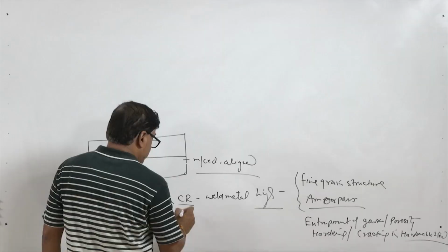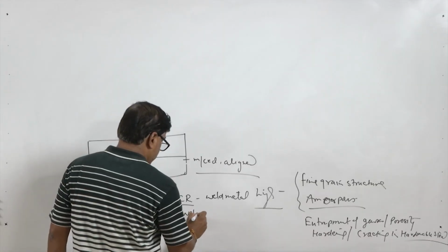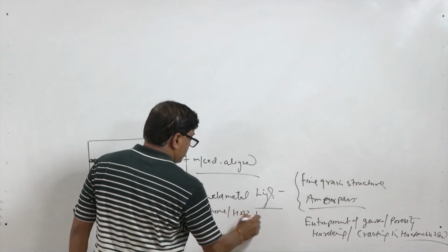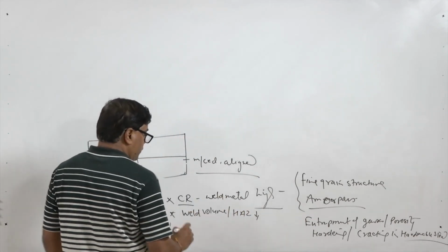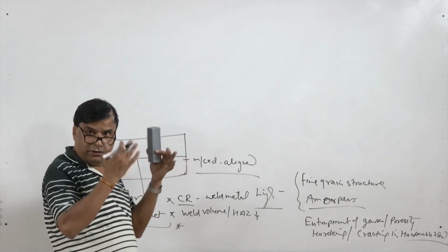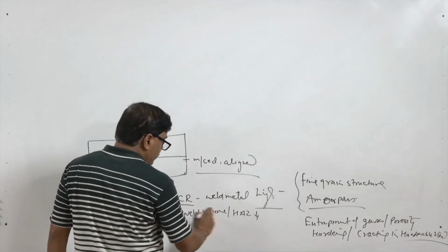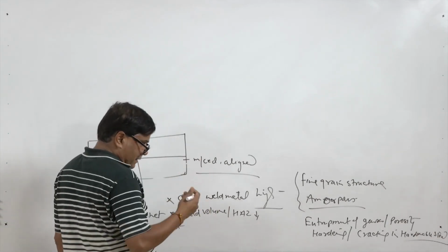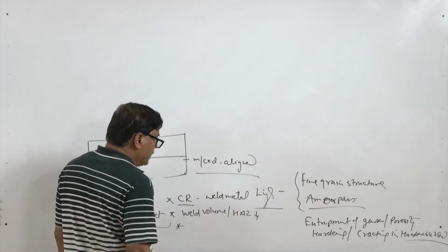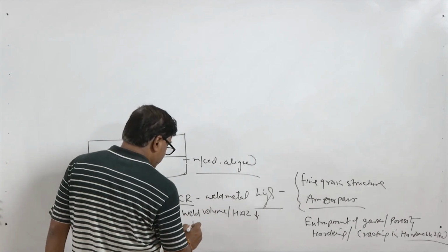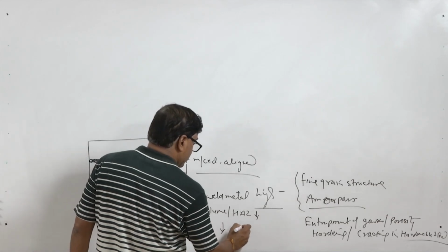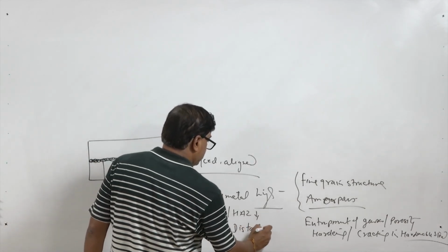Other attractive features of the process come from the reduced heat input. One factor is this cooling rate. Another is that the weld volume and HAZ are both less due to the reduced heat input. So, considering the expansion and contraction, the volume of the metal which is heated during the welding and then contracts during the cooling is small. This in turn reduces the residual stress volume, and reduction in residual stresses decreases the distortion tendency.